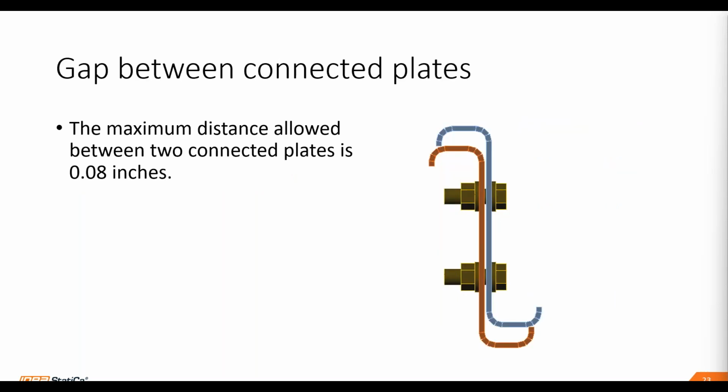Then another tip to consider when you're modeling is that the maximum distance allowed between two connected plates is 0.08 inches.